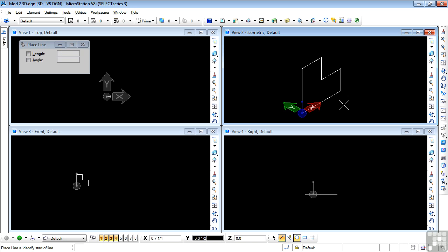What we've done is draw the front face of the step block, and we've rotated the compass to the front orientation with the F key, which is an AccuDraw shortcut, so that we have the compass in the front plane. All of which is very, very important.